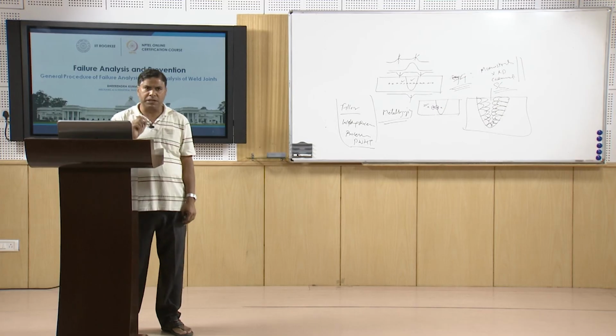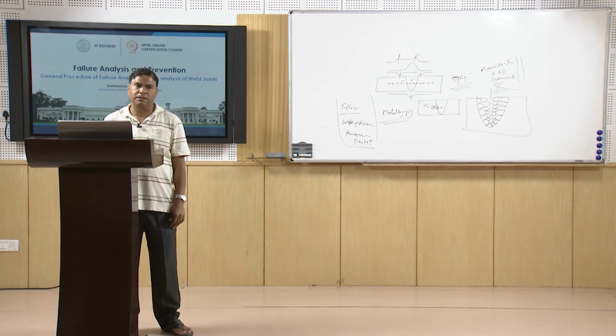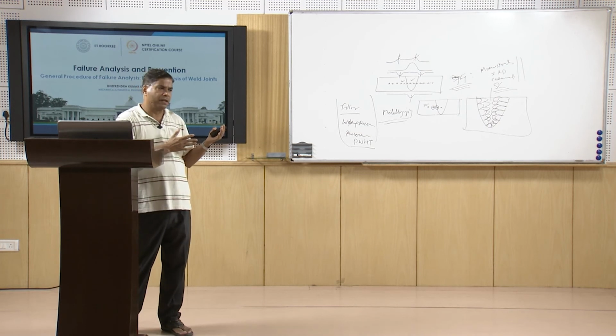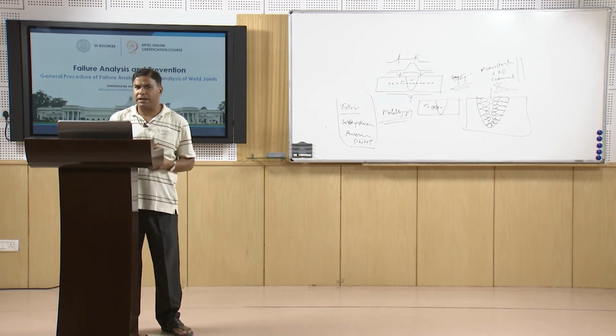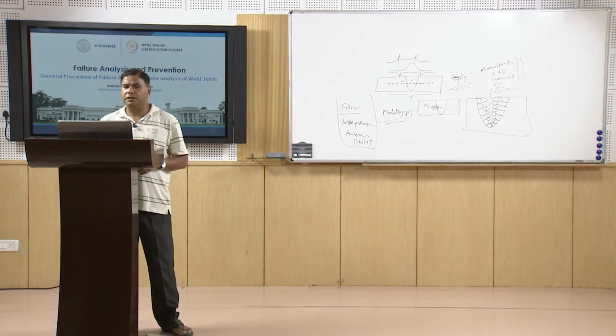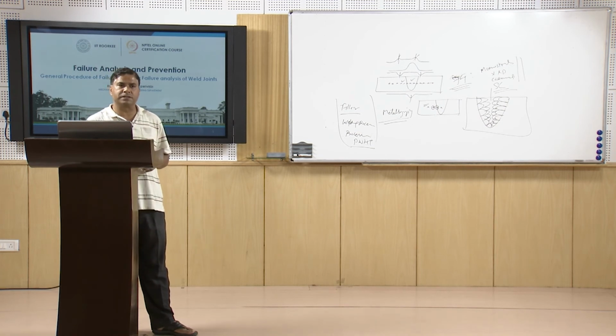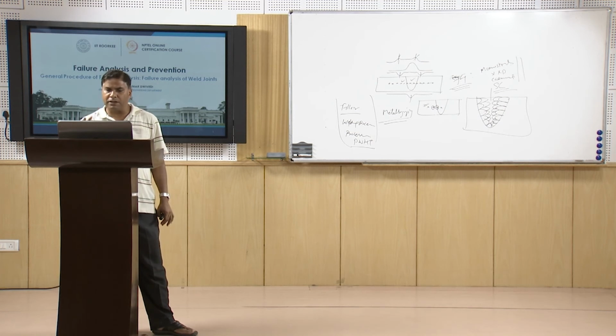Basically we have to see if any discontinuity is present and what is the possible role of the discontinuity. That is what we can analyze through the use of fracture mechanics. If there are residual stresses near the fracture location, near the fracture initiation site, then they can be attributed to the triggering of the cracking and then its growth.